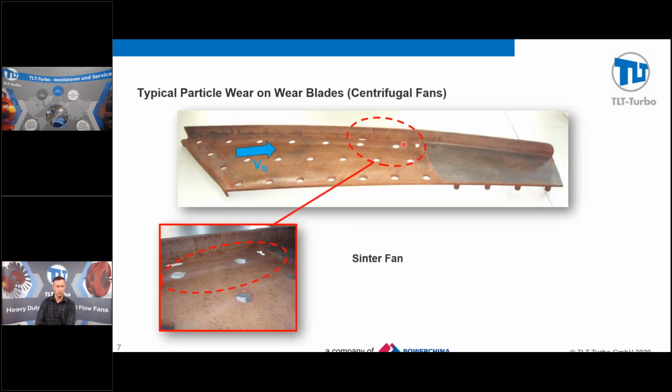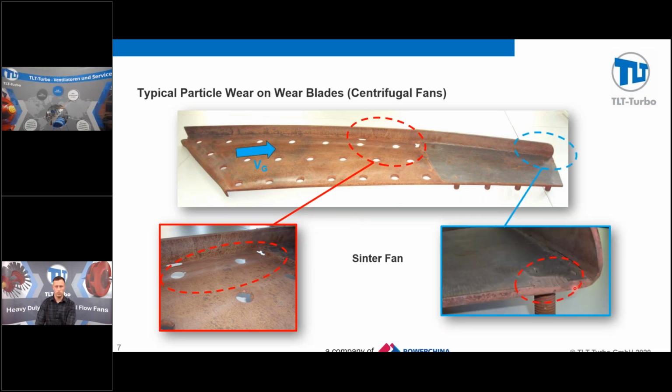And this is going to be thinned out, and then it's also going to travel along this line, and you're going to see a large loss in the leading edge and on the main surface. And then it's going to start cutting its way into the trailing edge. So you're going to see that it's going to start grooving in different patterns in the trailing edge depending on the airflows with the wear plates in the system. So design, layout, and the way the fan system's moving the air plays a large role in where the actual isolation of the wear goes in the fan system.